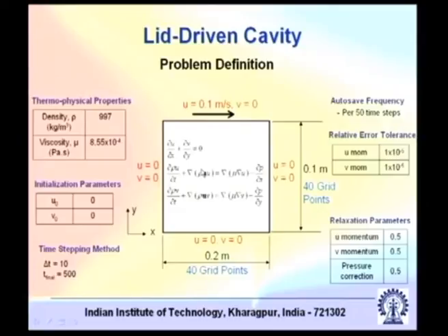So now you have to model the problem. So what is modeling? Modeling is basically idealization of a practical problem with certain assumptions, that is what is modeling. So you model this problem by considering that it's an incompressible flow, for example, or it's a special case of an incompressible flow where you have the density as a constant, because you may also have variable density incompressible flow, but this is a special case where you have density as a constant, and viscosity is another property that you require.